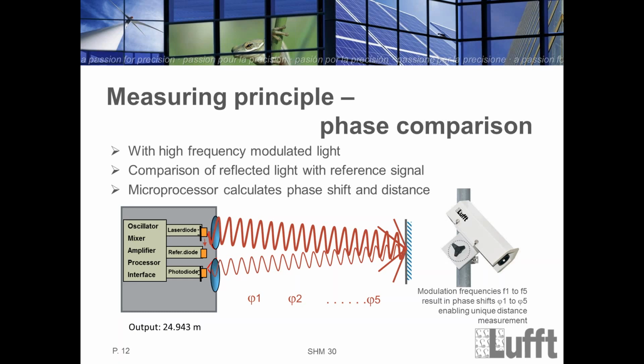You have to note that the laser is traveling, or different waves are sent out, and then these waves are analyzed and compared. Actually, 5 different wavelengths or frequencies are used. Also important to know is that the reflection, the time which comes back, is what gives the measuring result. In the setup inside, you can see that there are 2 lenses, one with the diode to send out, and here it is received.